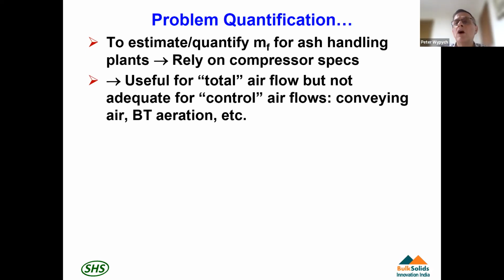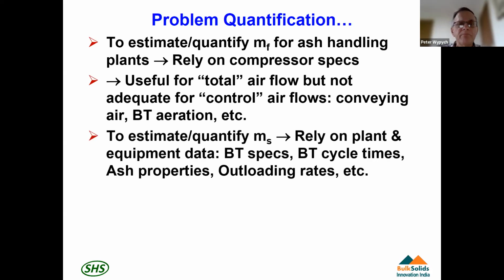And so then we know what the total airflow is going through the pneumatic conveying system. But it doesn't give us any information or detail on the distribution of air, like Dr. Malik showed, how much air is going into the conveying line, how much goes into the blow tank and so forth. And as Dr. Malik indicated, that information is quite important. And I'll come back to that in more detail with some pictures. But as I said before, I warned you, I'm going through a lot of checklist information here.